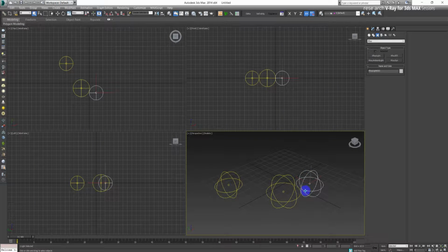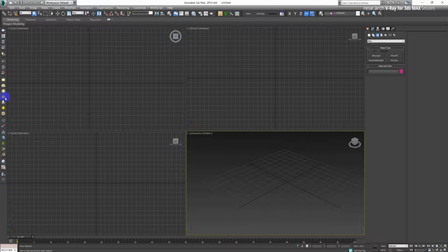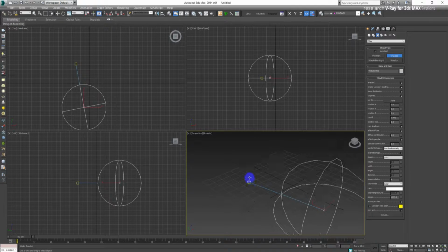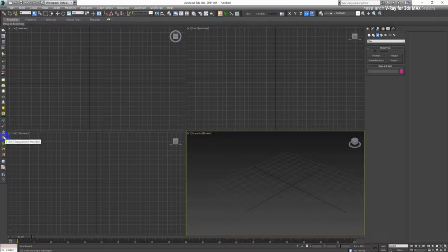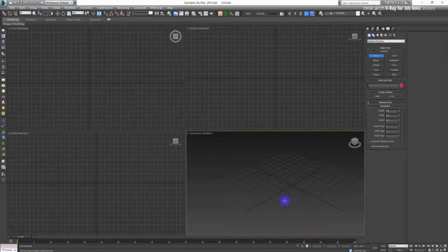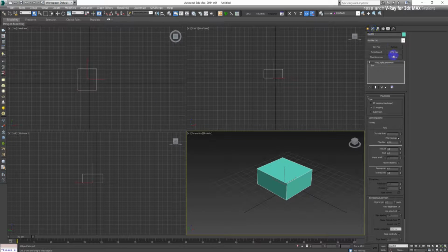Spheres, right? And then we have a mesh light, IES. We are going to cover all those later on, but it's exactly the same situation. So just click a button and drag it into your scene and apply. There are also here some modifiers which you first need to have selected some geometry for. So let me make a box, and when you click on a modifier, it applies the V-Ray displacement modifier right here.